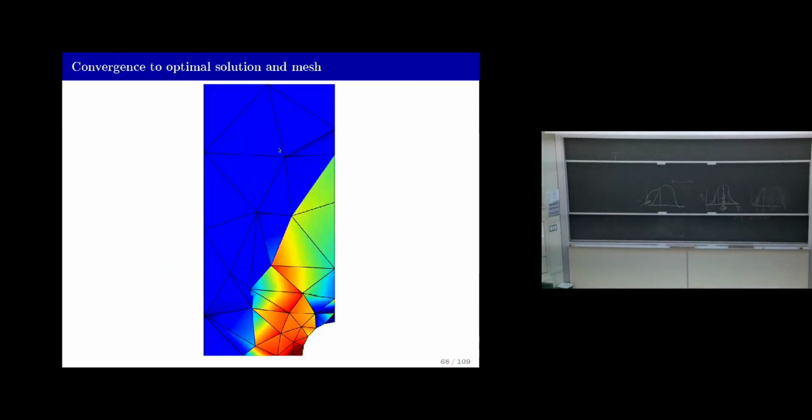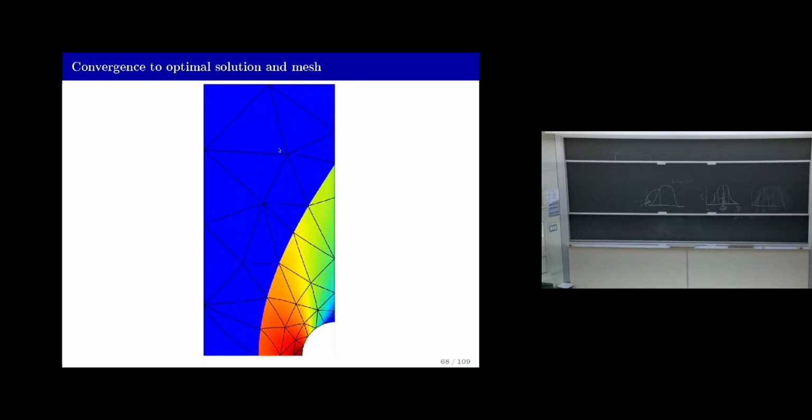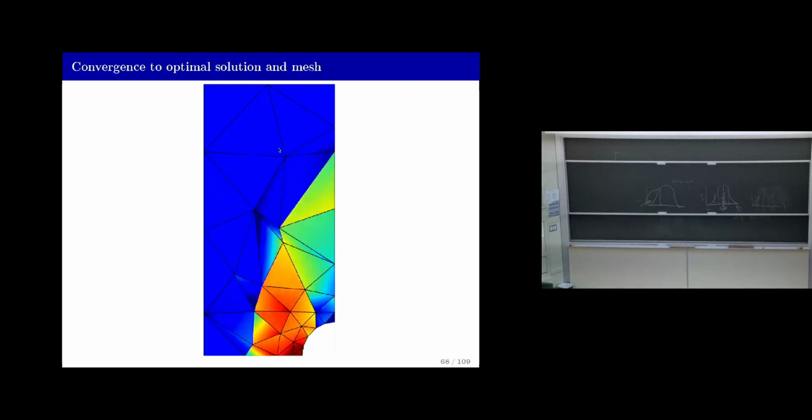So now let's just look at a movie of how this converges. It takes quite a few iterations in this case, but that's not uncommon for optimization approaches. What's key here is that nowhere is this a valid solution until the mesh converges. We're always iterating both the mesh and the solution until they both converge together. And then voila, you have the solution. And like I said, this is critical for this approach to work. We couldn't do a nested approach because of simulation crashes.